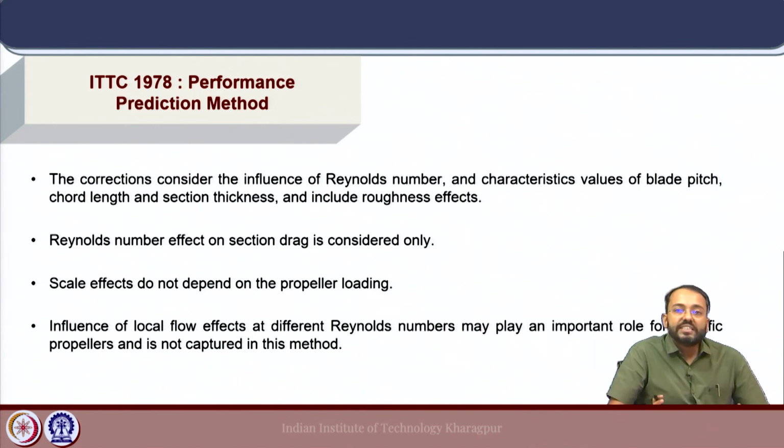So, this gives an idea of the propeller performance in the open water condition and its testing for the open water test, and the extrapolation of the propeller open water diagram using a standard procedure from the model scale to the full scale. In the next class, we will continue with self propulsion test.